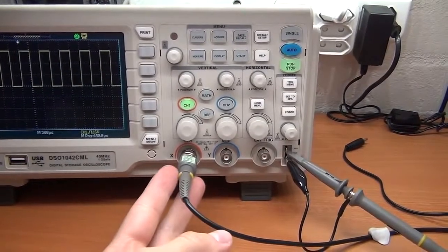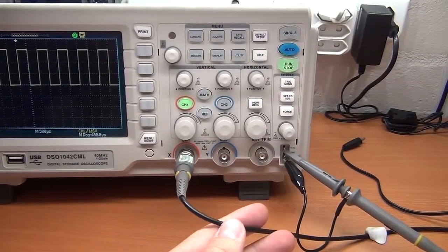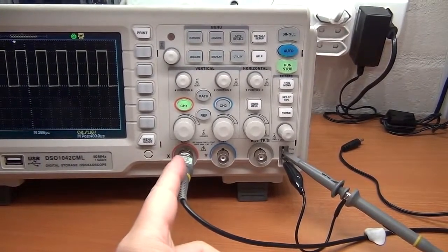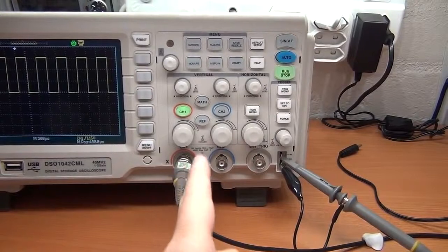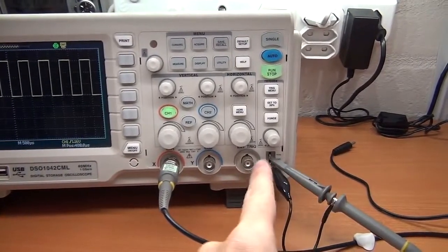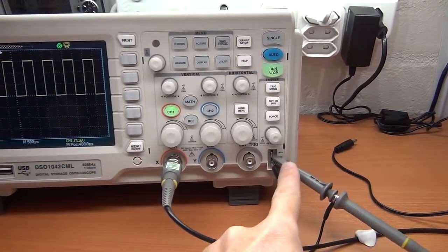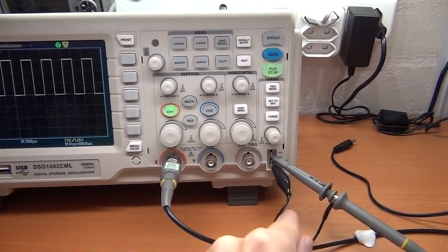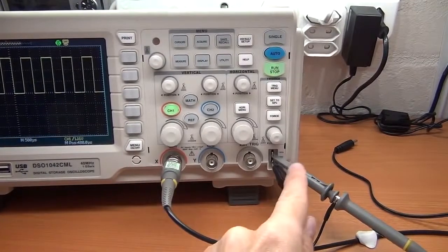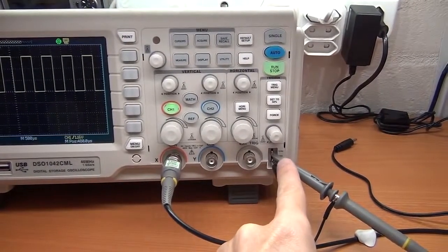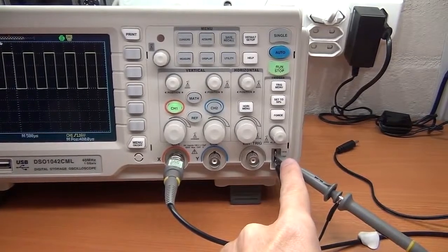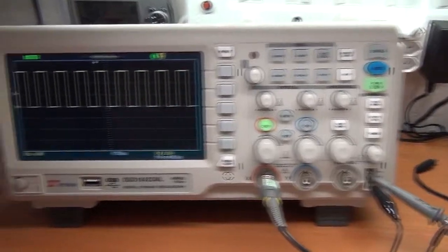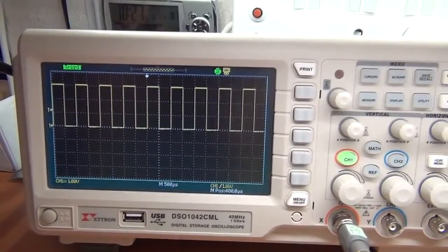But your oscilloscope probe is where you're going to pick up your signal. And this oscilloscope happens to have 2 channels. I'm just using 1 channel, which means we can actually view 2 signals at the same time. Your probe is what you'd connect onto the signal you're measuring, and then you have another lead, which is in essence the ground lead for the signal. So I've got these connected to a reference signal which you can use to calibrate your probes with, but it makes a nice easy sample signal on the actual scope itself.